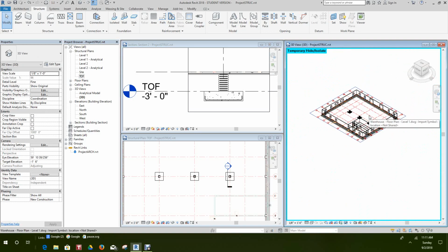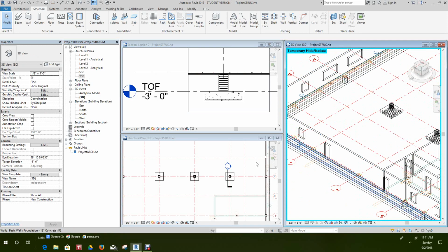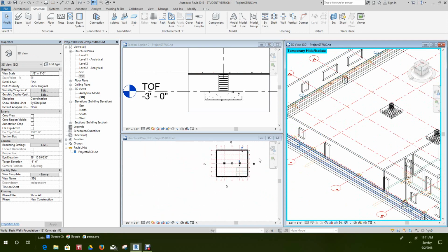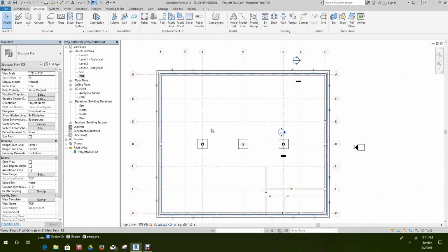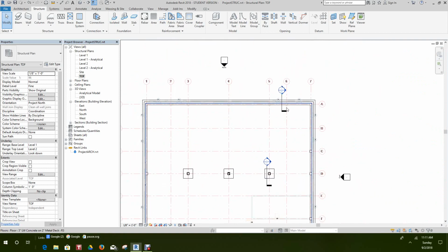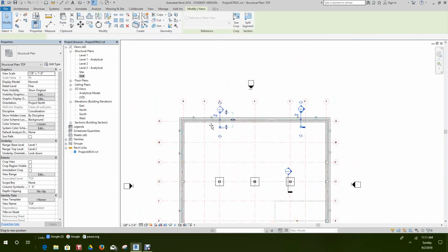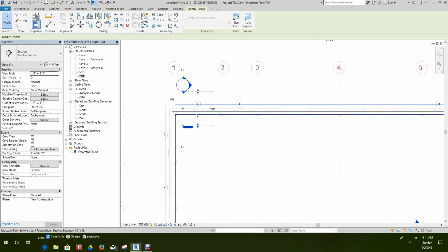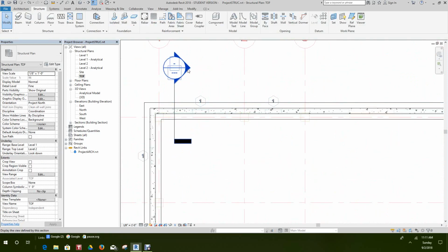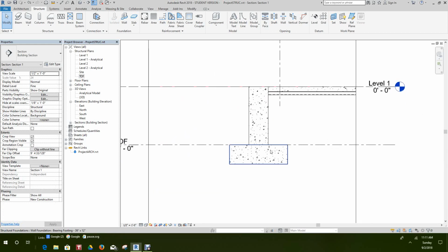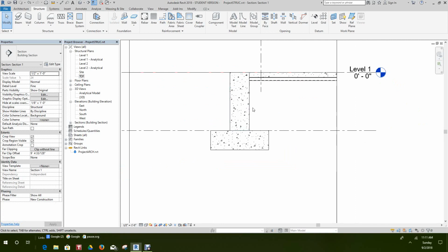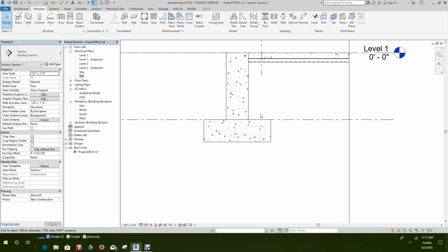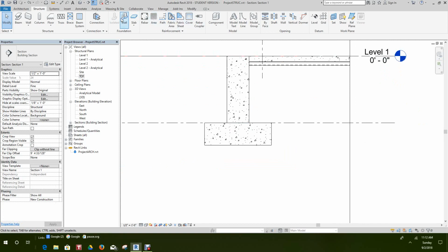Now let's take this a step further here. I wanted to make this a 2-part, but we're going to split the parts from architecture to structural. So let's do this wall. Let's take this section up here that I had already placed. Let's double click, and there's our wall and footing. Here we're going to do something a little different. We're going to use our sketch command with reinforcing on this one.